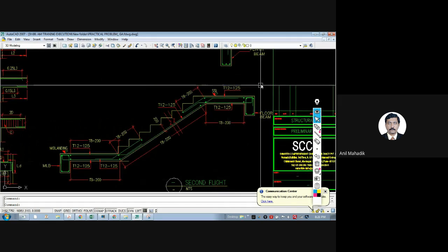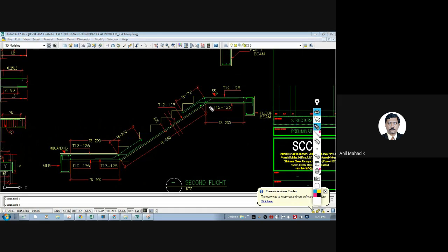Now you'll see the small detailing part is always important. This main steel is going like this, and this horizontal steel is going like this, so there is a crossing of steel over here. This is to avoid the cracks which will happen here. As this tries to bend, there is tension in this direction and in this direction, correct?